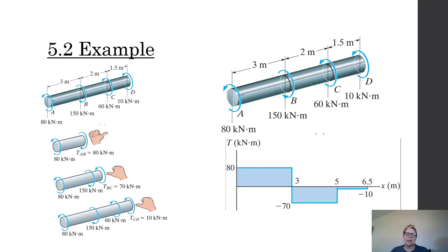And now I know that if I'm calculating shear stress, there is a positive shear stress and a negative shear stress. If I have negative stress, I know that my angle of twist is negative. If I have positive stress, my angle of twist is positive. On the cake problem, it's a little easier to see tension and compression, but once we start adding twist in, you have to keep up with positive beam notation so that you get the correct sign on your torque, because there's a huge difference between a positive angle of twist from positive shear stress and a negative angle of twist, okay?